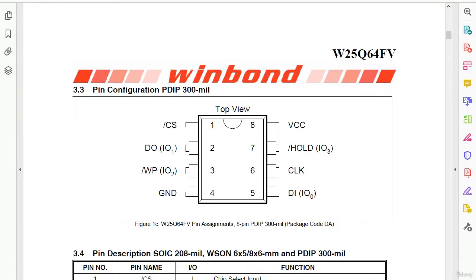Hi again. So in this lecture, we're going to see the BIOS chip pin configuration. We're going also to see how to download the circuit diagram of every BIOS chip you want. We're going also to see the schematic of the BIOS chip, and of course we will see some real BIOS chip in the motherboard, and we will use the multimeter to check its pins, to check the VCC pin, and of course to check the ground pin, etc.